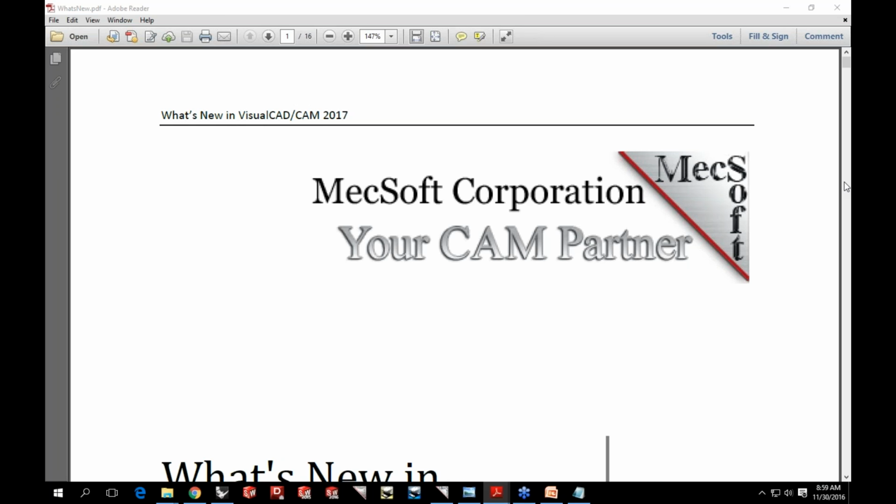That's a great question. If you save your machining operations to a knowledge base, then load the knowledge base, those settings will be loaded from the knowledge base. Your knowledge base could contain just a single operation or multiple operations. You could just have a work zero defined under your setup and then save that to a knowledge base, and loading the knowledge base will load your machine definition automatically in.